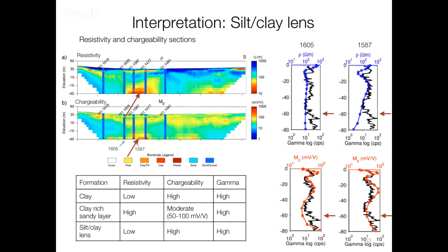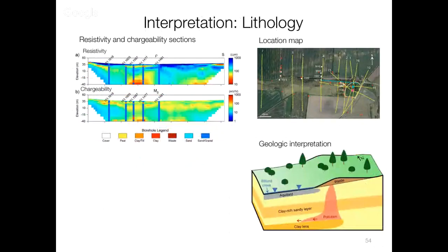it might be that it really is indicating a region of lower resistivity, and it doesn't seem to have much chargeability. That will ultimately be interpreted as perhaps being leachate that's there. And all that's kind of captured in this cartoon geologic interpretation that they've got.